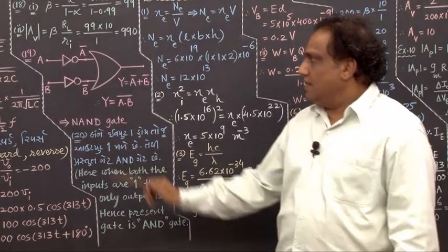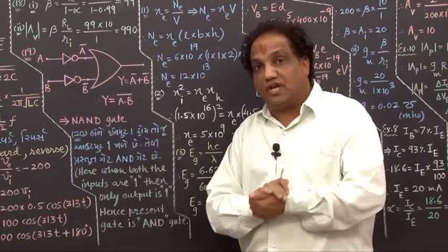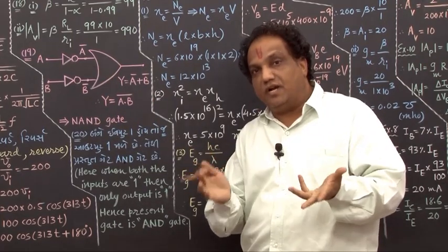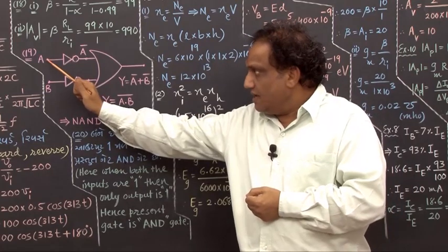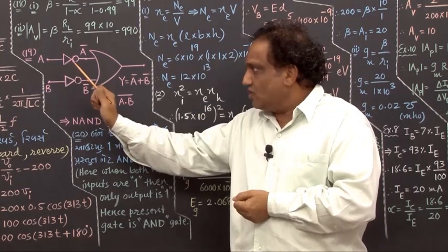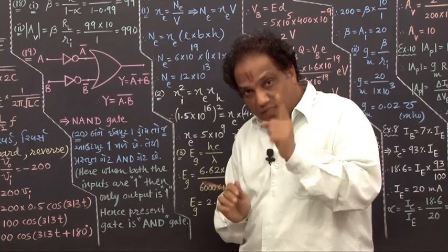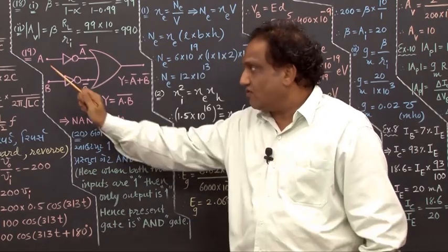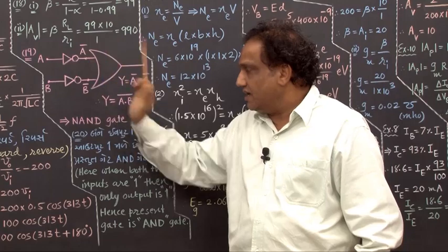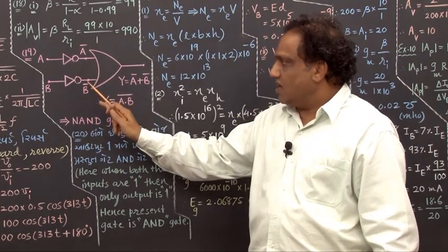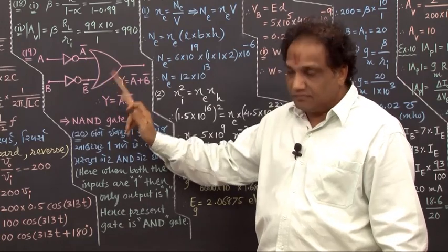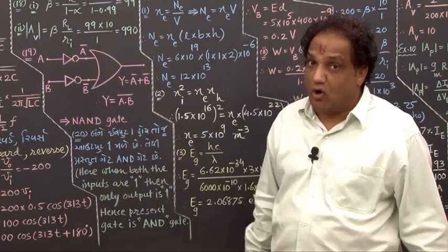Read it. They have given this sort of logic gate, and we are asked to find out the name of that logic gate. Let us find out. Here inputs are A and B. Because these two are NOT gates, they would perform NOT operation. So from A you will get NOT A. From B you will get NOT B. But these two are now inputs for this OR gate, and you know OR gate will perform OR operation.